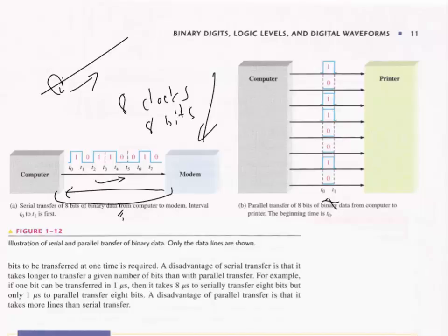Nowadays, almost every hard drive out there, pretty much everyone I know of, uses some form of serial ATA interface. So parallel has more or less disappeared when it comes to interfaces outside of the computer system. Once you're internal and on the same piece of silicon or the same board and very close, crosstalk ceases to be such a problem, and then you will see parallel. On a computer motherboard, for example, the interface between the RAM and the microprocessor is going to be parallel.